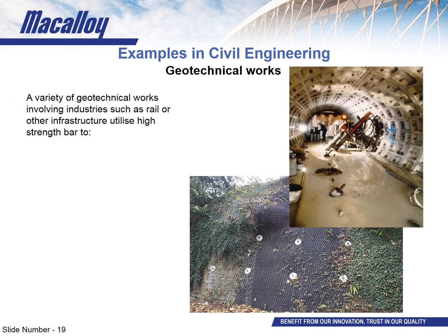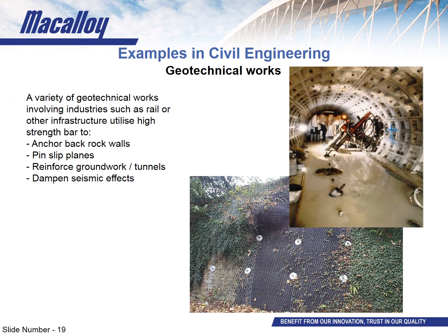performance. Post-tensioning bars or other high-strength studding such as our S650 bars are used in a complete smorgasbord of geotechnical applications. These include rock anchors for holding back sections of cliff or rock face, soil nails in order to stabilize ground conditions on slip plains or other loose earth, reinforcing sections of ground or concrete in areas such as tunnels, and also to assist in seismic damping to act as the main load resisting element.